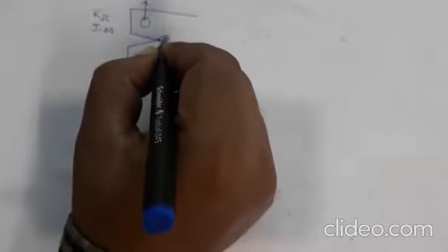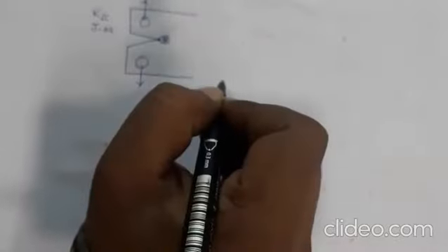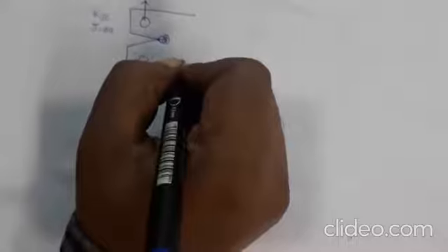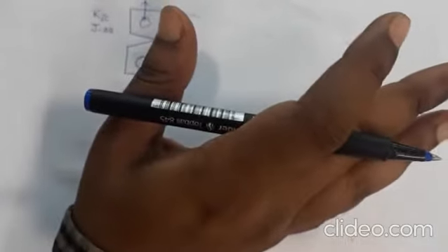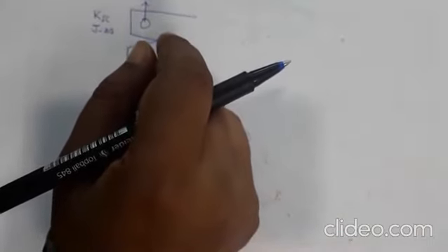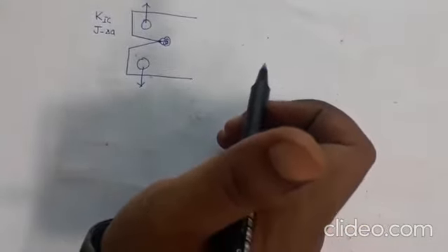Still, instead of just opening up in monotonic loading and creating a sharp crack, applying fatigue crack growth is better. So that's an advantage of fatigue crack growth. Other than that, in structural components, fatigue crack growth is not an advantage. You want to avoid such situations where you have crack growth.